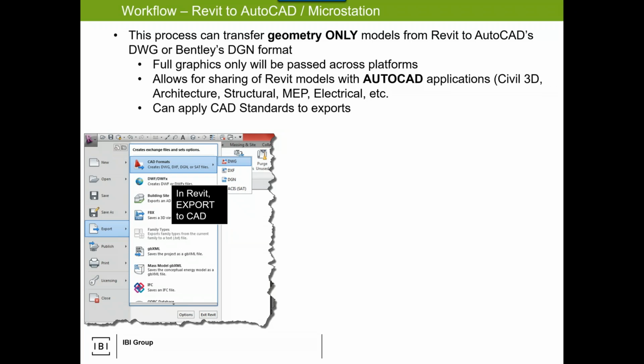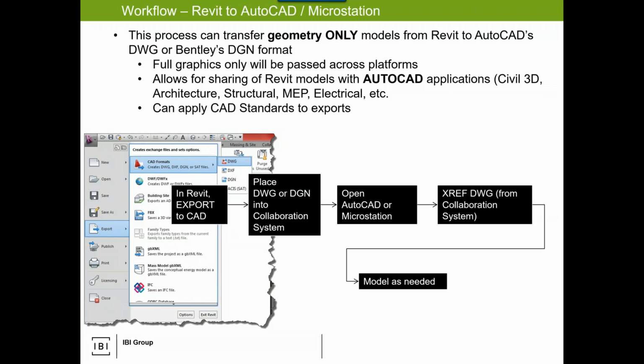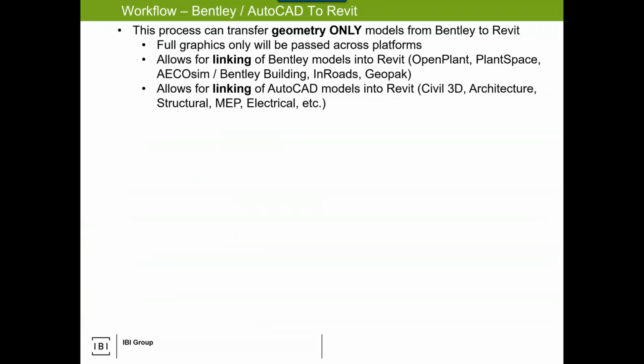And if you have been in Revit, export to CAD, you can select your item, then you open up AutoCAD and you get your stuff in there and you can link it in your system. The challenge there is the intelligence gets lost. In Revit, it's very explicit, export to CAD. So you're losing BIM. Even though you have 3D graphics, you're losing a lot of the intelligence. Not the same as the IFC export that's deliberately designed to maintain information.